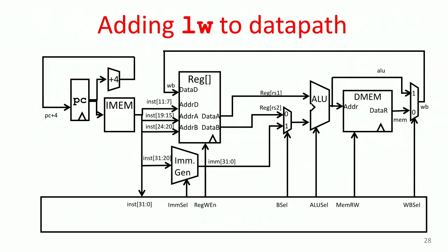Yeah, and it's pretty much just what I said. We take the address, the output of the ALU, it gets split. There's fan out here. It goes into the MUX, so it could find a path back to the register file in the case of the arithmetic immediate instructions. Or it could get used here as an address in the case of the load instruction. In that case, the data comes out here and it also goes into the MUX.